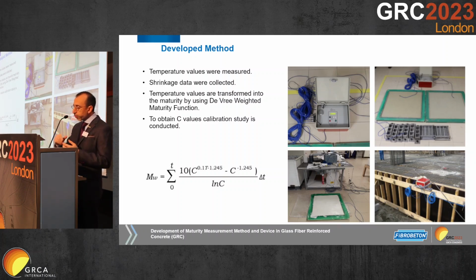We tried values regularly between 1 and 2 in small intervals such as 1.05, 1.1, 1.15, and then we targeted the best available C coefficient in order to use in the general equations. Moreover, at the same time, with the same mix design, we collected shrinkage values using a 1 meter shrinkage mold, 1 meter in length, with a 60 by 100 millimeter cross section.